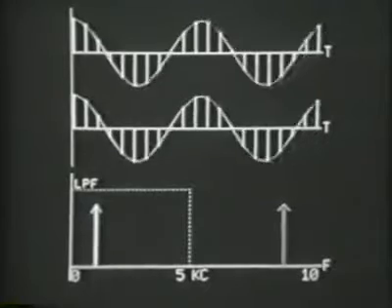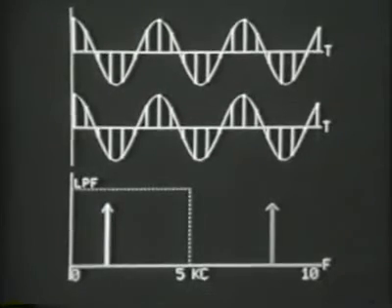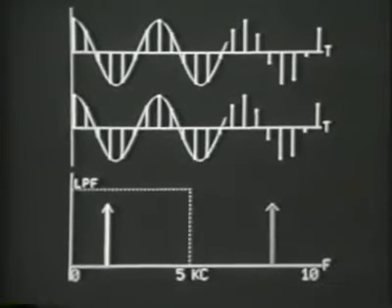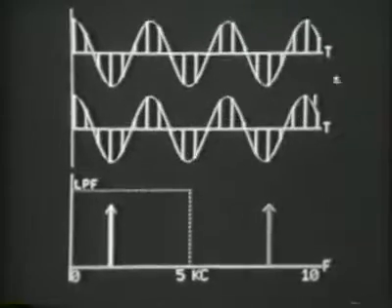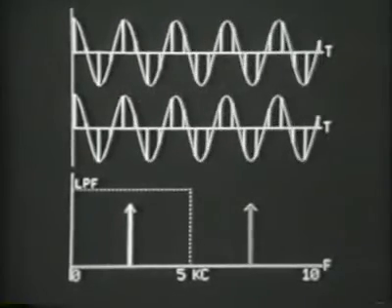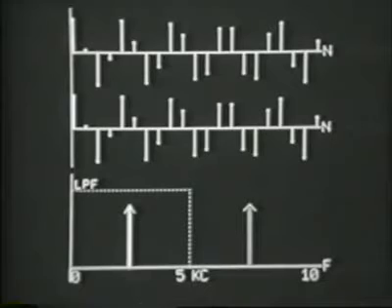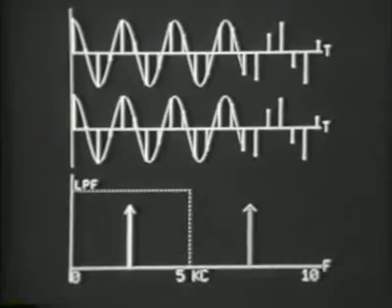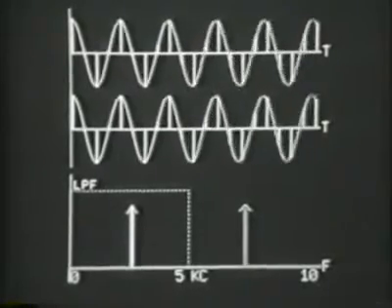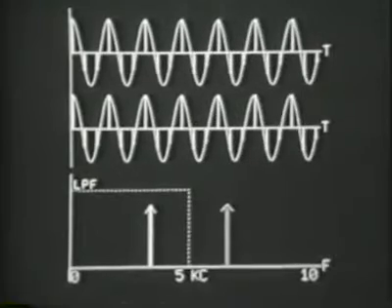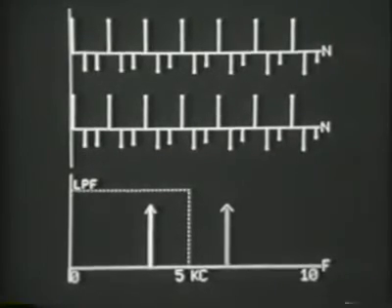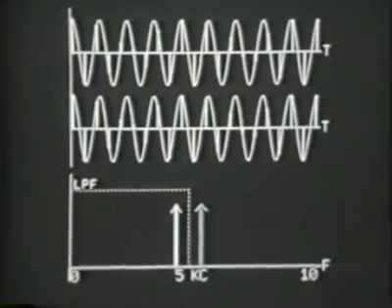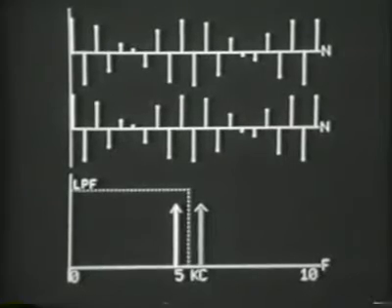We now increase the frequency at the input. The reconstructed sinusoid tracks the input in frequency, and of course the samples of the two are identical. The interpolation in between the samples is identical because of the fact that the input frequency is still less than half the sampling frequency. And so as long as the input frequency is less than half the sampling frequency, not only will the samples be identical, but also the reconstructed continuous waveform will match the input waveform.